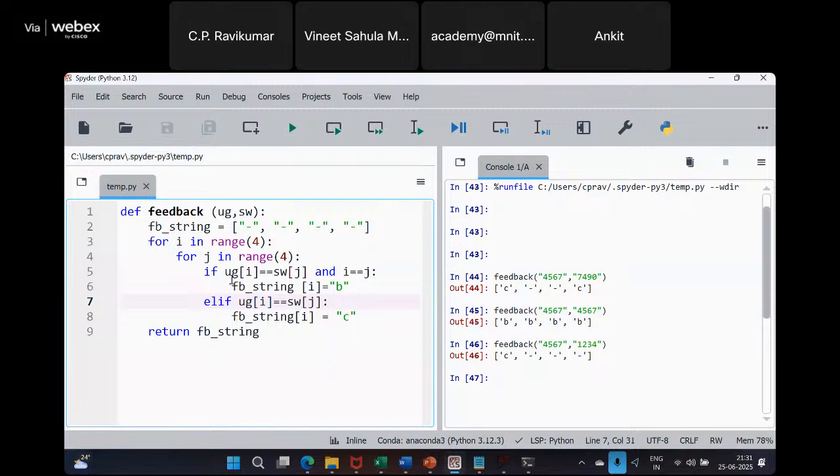So imagine that there is a bug in this program, right? And then I'm trying to verify the hardware and I'm complaining that it doesn't work. But the reality is, the verification program has a bug, right? So the verification language, okay. So there is a HDL, hardware description language, and there is an HVL, or a hardware verification language. So system Verilog is a hardware verification language, and you can use things like Python, C, C++, etc. also if you want.